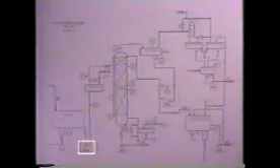After that, he closed the steam trap drain under the reboiler and opened the reboiler steam supply valve. In the next pre-startup check, the outside operator selects a reflux pump. As before, he lines up its valves and then checks to make sure it has electrical power. Then he selects a feed tank pump, following the same procedure he used for the recirculating pump and the reflux pump.